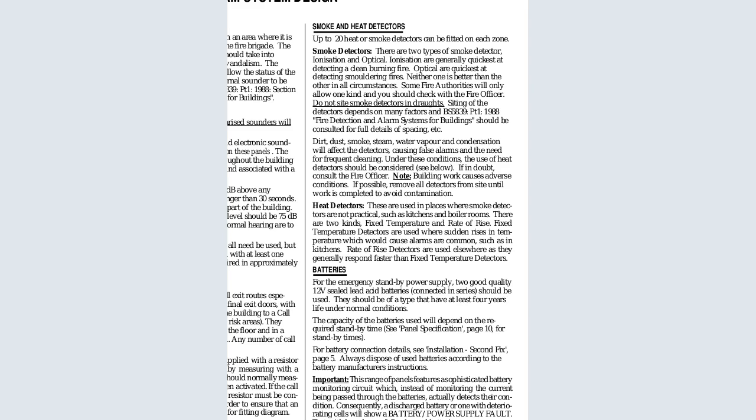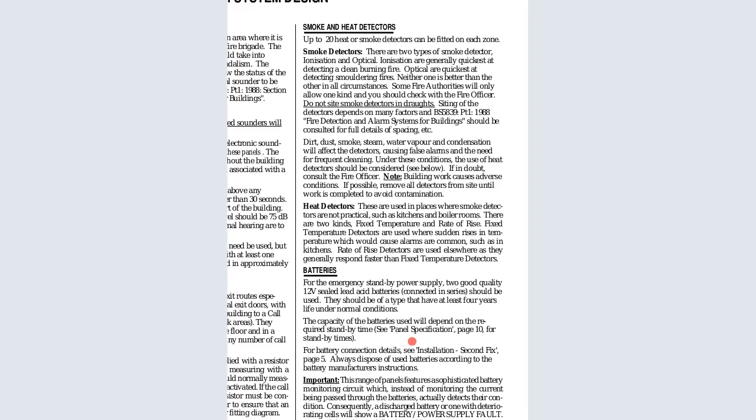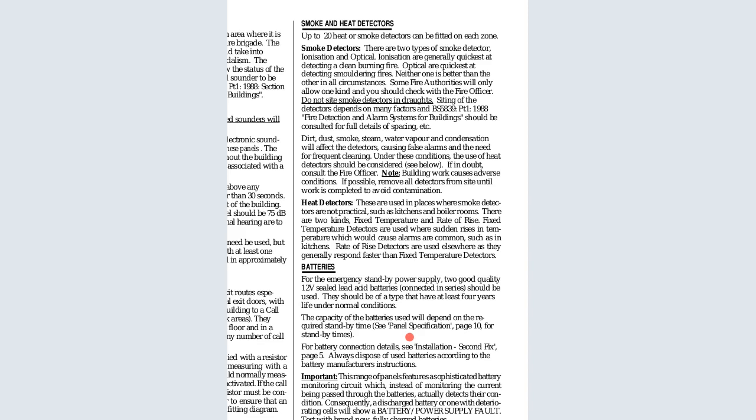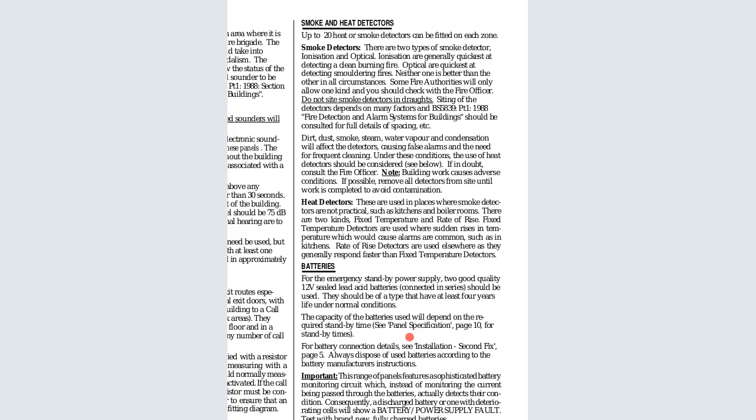It states that fire detection and alarm systems for buildings should be consulted for full details of spacing. Dust, smoke, steam, water vapor, and condensation will affect the detectors, causing false alarms and the need for frequent cleaning. So under these conditions, the use of heat detectors should be considered as below. Note that building work causes adverse conditions. If possible, remove all detectors from site until work is completed to avoid contamination.